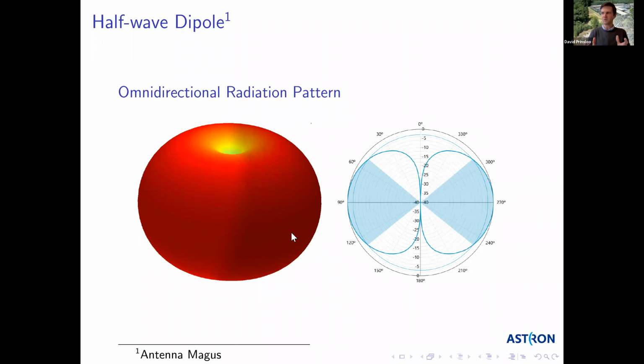Now, Mohammed, I guess I could come back to your question where you asked why is the power more in one direction than another? This is due to the current distribution on the dipole. So at a position where there's zero current, in a certain direction, there'll be almost zero power radiated. And if you have a maximum in a certain direction, you have maximum power radiated towards that point. And the same applies for aperture antennas in terms of field distribution, which we'll get to hopefully by today, we'll see.